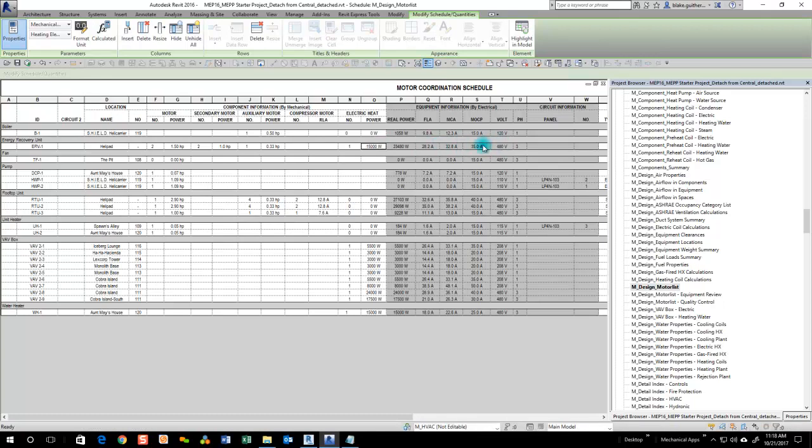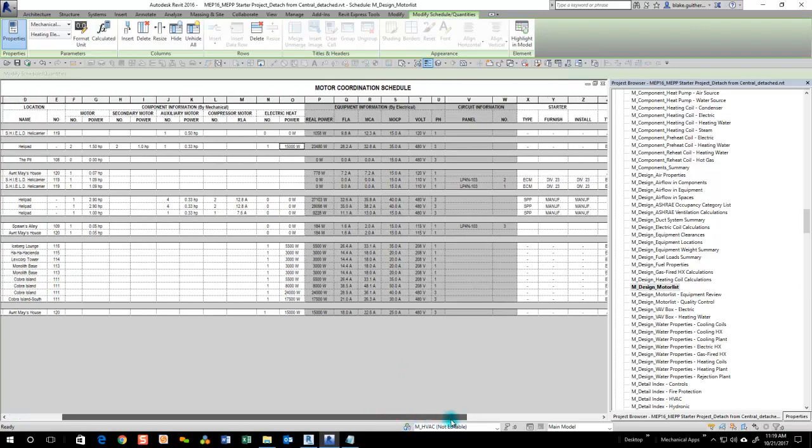So are these exact values that should be used for rated packaged pieces of equipment with multiple motors? No, not necessarily. Ultimately, that's for the electrical engineer to determine. However, me as the mechanical person, I'm giving him information up front that he can use as starting information, and then once a final selection is made where he gets his rated values, then he can go and override those.